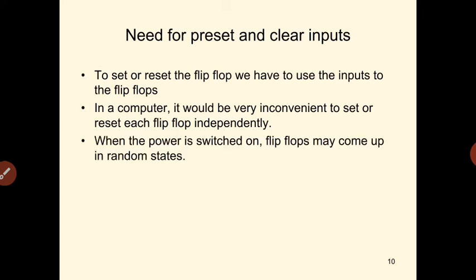That's why there exist some asynchronous inputs called preset and clear inputs, so that whenever you are presetting the circuit, all the flip-flops' outputs will become 1. That is the meaning of presetting. When the power is switched on, flip-flops may come up in random states.